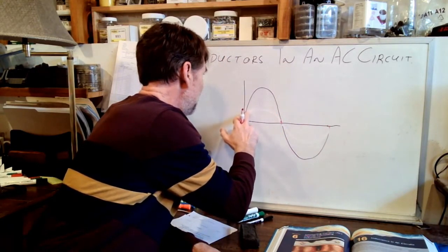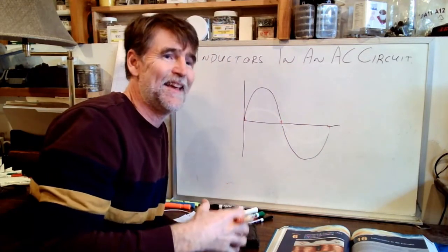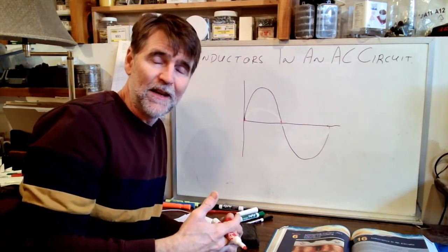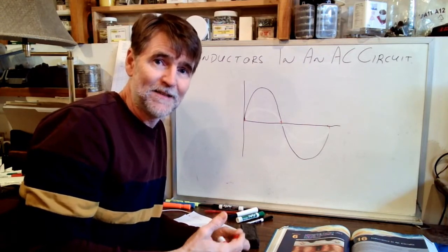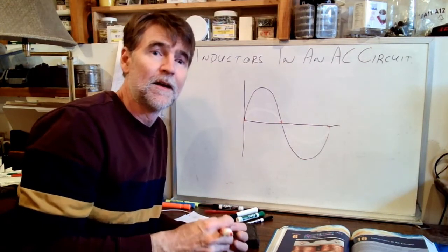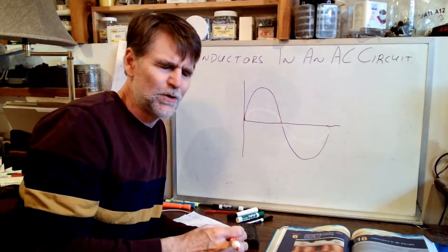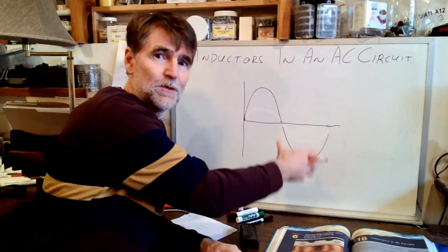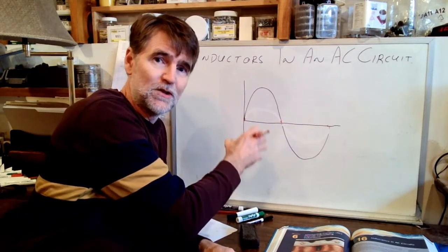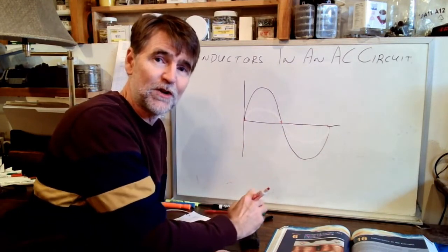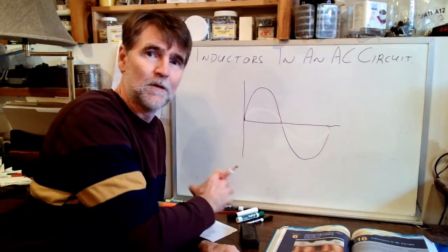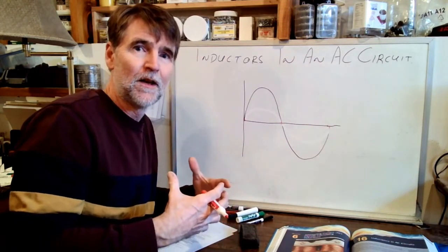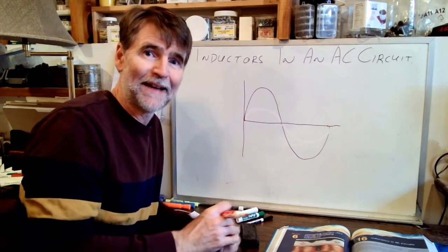But because it takes time for the current to build as a result of that induced voltage pushing back against the applied voltage, giving us only the resultant voltage, so you've got the applied voltage, you've got the induced voltage, you have the effective voltage left to actually push the current. And it takes time for that to build because of the Lenz's law inertia kind of effect, pushing back against the change.